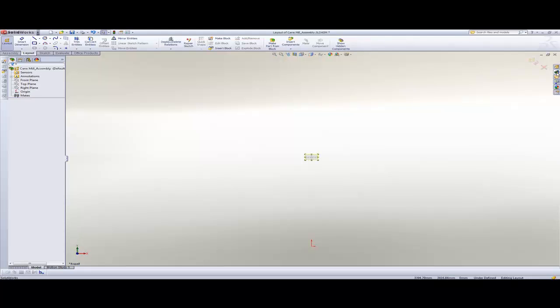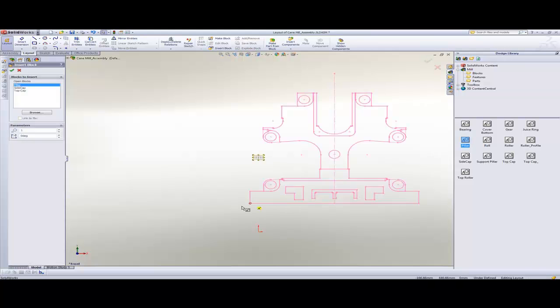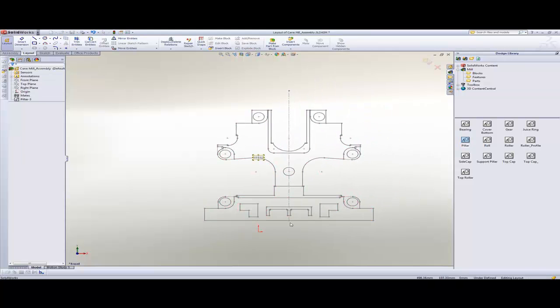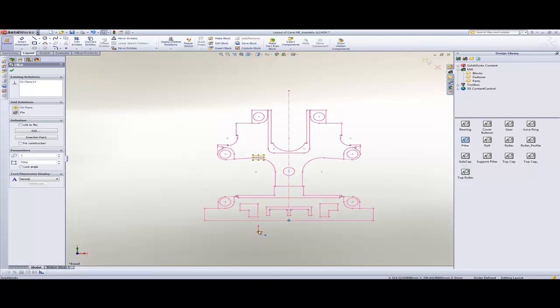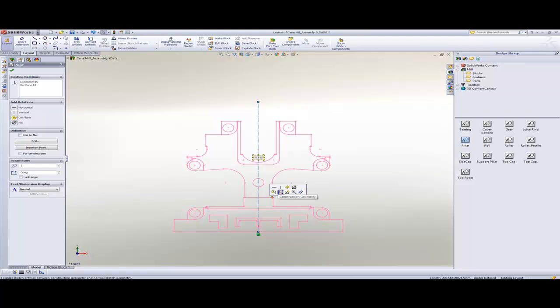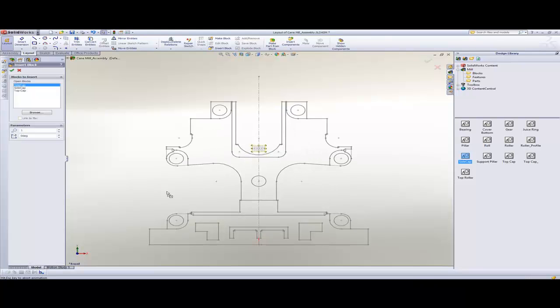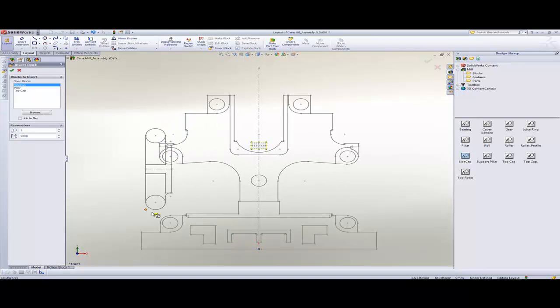Most of the time, a machine design process starts with a layout. We too are starting with a concept. 2D blocks in SolidWorks can be added to our design library. Just by dragging and dropping them from the library, a quick layout can be formed. It also helps us to simulate motion between relative components.